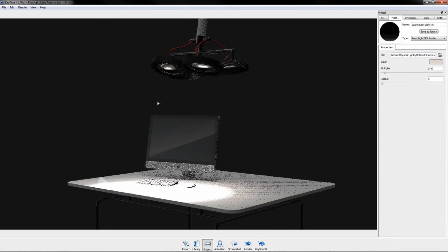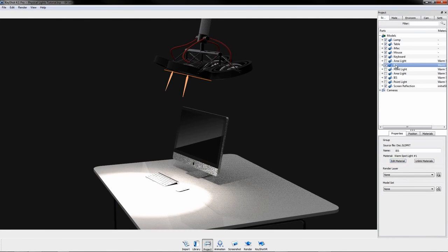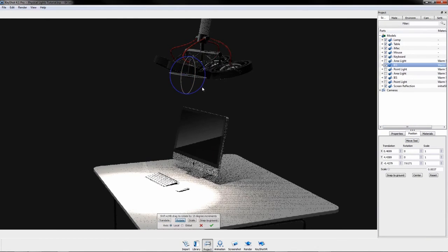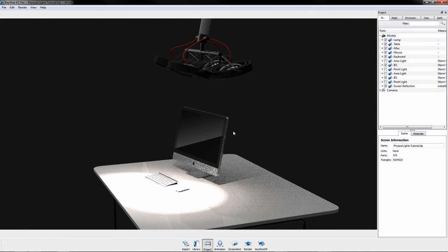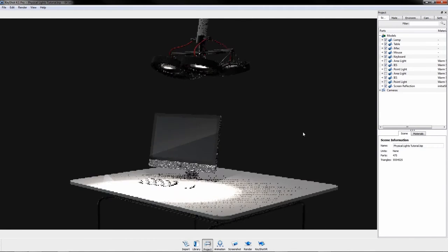The direction of the projected light is on the individual part's negative y-axis. This means that you must rotate the part to change the direction of the light. So if you're applying this type of material to an existing piece of geometry, you may want to apply it to a duplicate of the original part, or an imported primitive so you can make position adjustments without making changes to your original import.